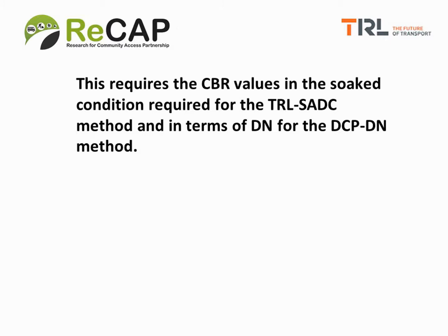This requires the CBR values in the soaked condition as required by the TRL-SADC method. This does not mean that we believe that the road will have soaked CBRs in its operating condition, but it's a simple way of actually identifying the qualities of the individual subgrades. The values we would use in this example are shown in the next slide.